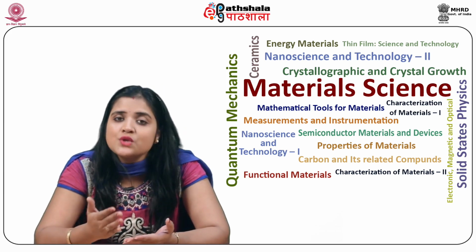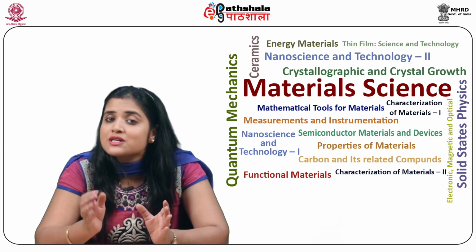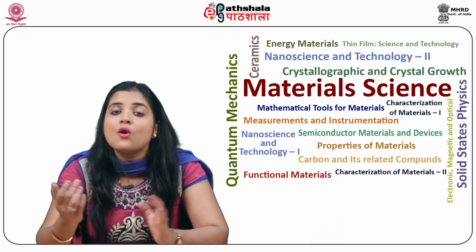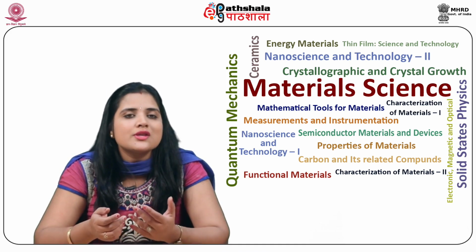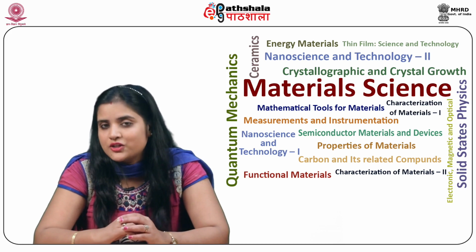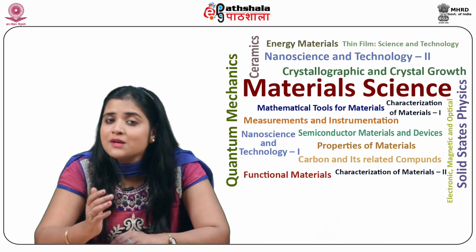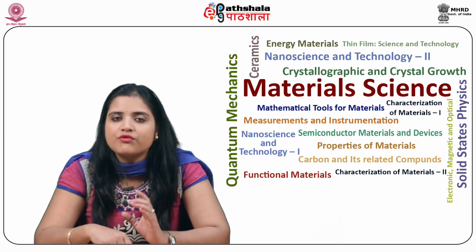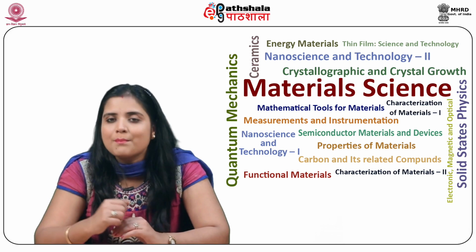However, it suffers from a limitation that as the number of digital bits expected in the output increases, or the resolution increases, more and more comparators are required. That is, for n bits, 2 raised to power n minus 1 comparators are required to perform the desired conversion. For example, a 3-bit digital output requires 7 comparators.